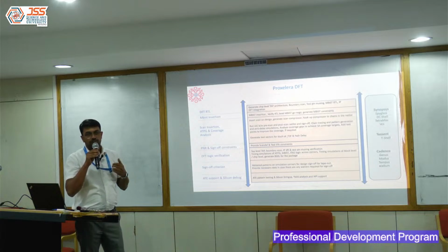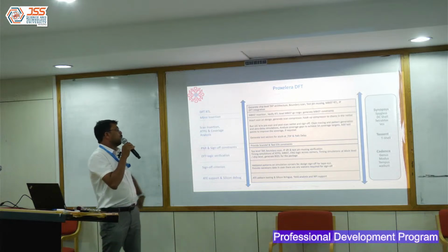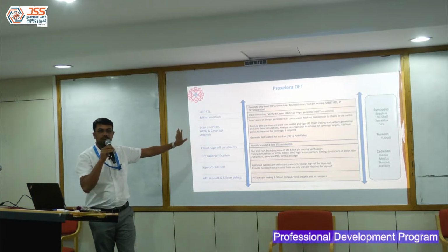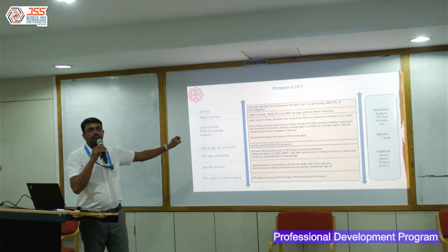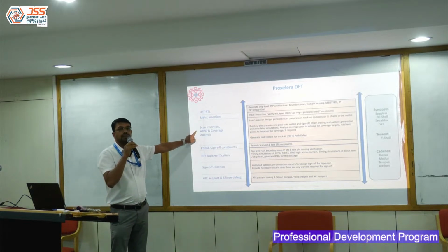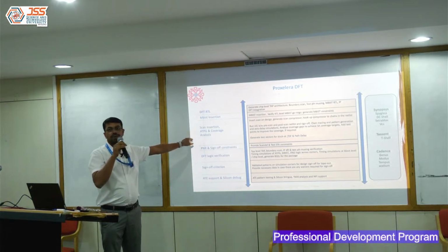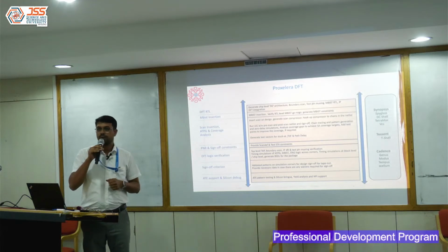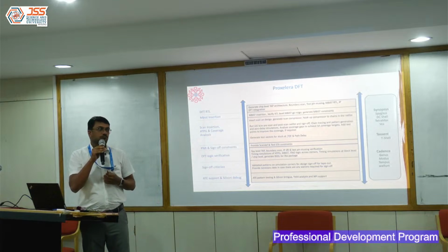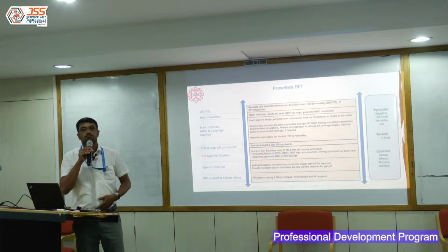Now how does a scan chain work? A scan chain works exactly the way your shift register works. It's nothing but a huge shift register. One important thing that comes here is, you might have heard about compression. I don't know how much you have heard about compression, but basically my test time, the time required to test a particular logic, depends on the length of my scan chain. So the longer the scan chain I have, the more my test time will be. So one requirement that is a must if you want to bring down the test time is to go for compression.